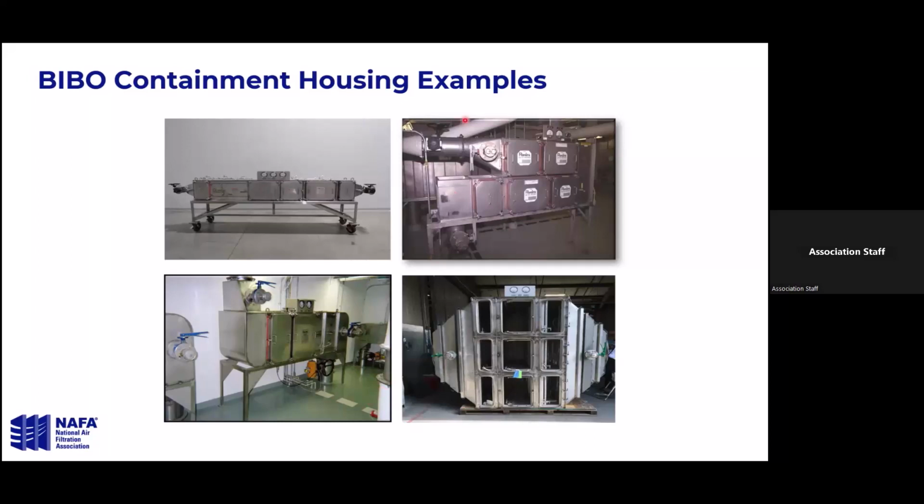Some of these housings you'll see have manual dampers, like these two here. This particular housing has a manual actuator on it, but it's a override for that manual actuator. It actually has a pneumatic actuator on it. So on these dampers, you can do just manual actuators, electric actuators, pneumatic actuators.